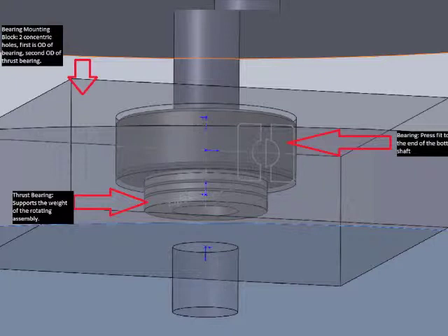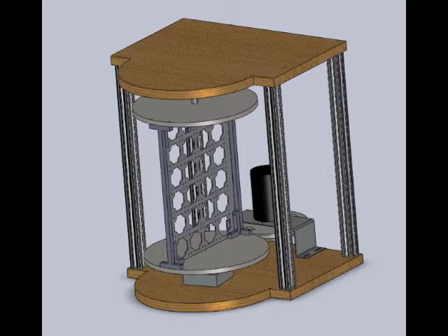The I-beam assembly will be built and tested on the lathe between the 18th and 25th of this month in order to determine if the amount that the design will vibrate is acceptable. 3 pieces will be built: the bottom disc, which will connect to the chuck of the lathe, and 2 I-beams to connect the top and bottom discs. The top disc will connect to the tailstock of the lathe.